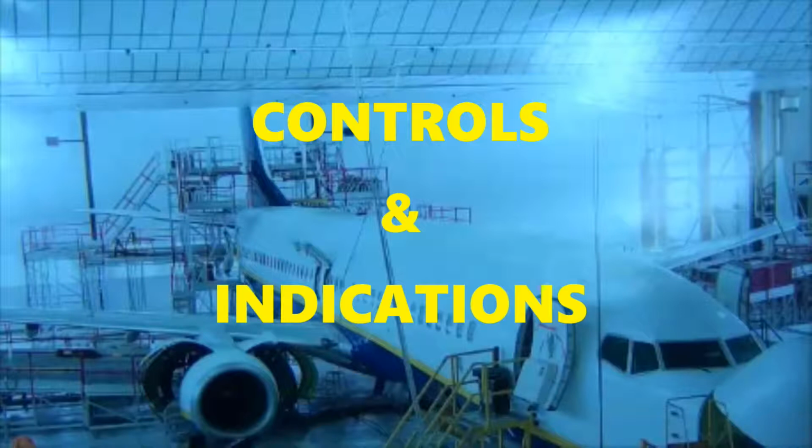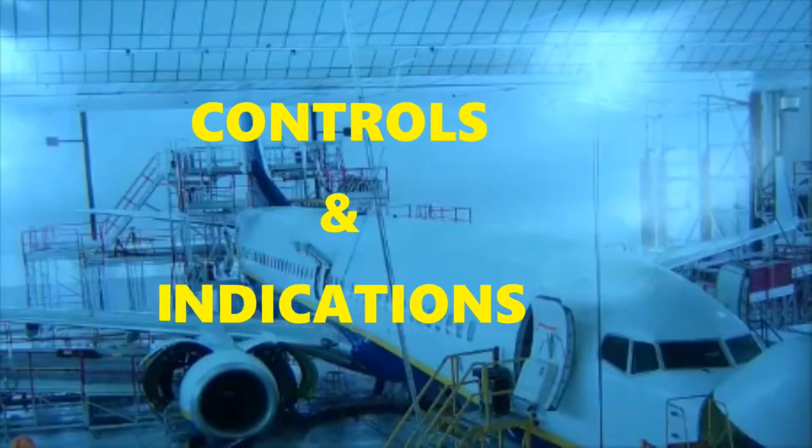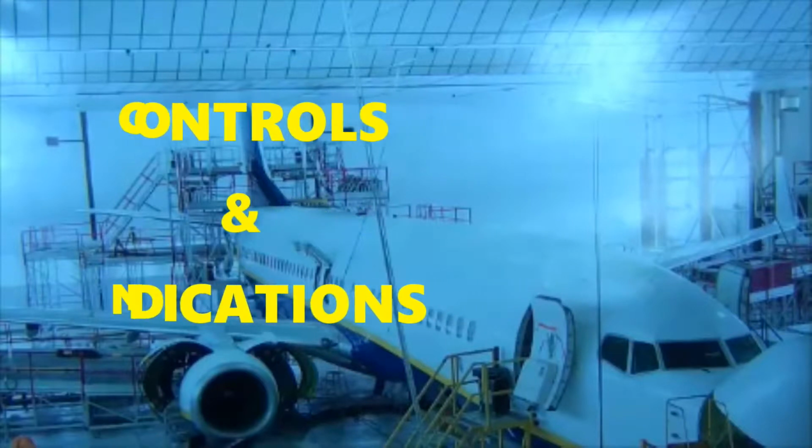Now, above that, you're going to see the push buttons for the engine and the APU fire. So you've got engine fire and APU fire push buttons, which is important. Remember I said you want to shut off fuel if there's an indication of a fire or something related, we don't want to have a continued flow of fuel when there's that situation. So those push buttons are located right above the fuel control panel for convenience. And so again, those are basically the shut-off valves to shut off that flow of fuel.